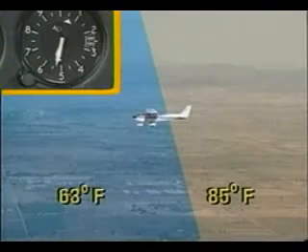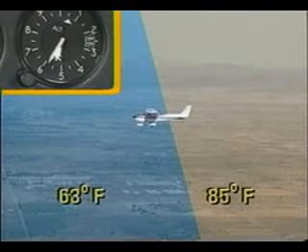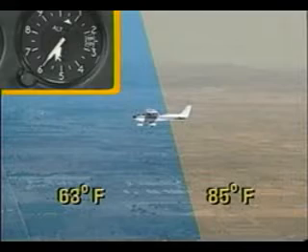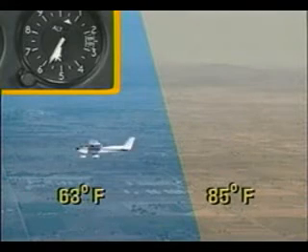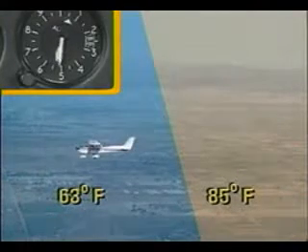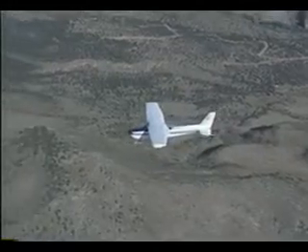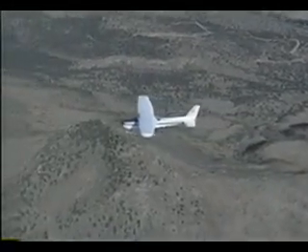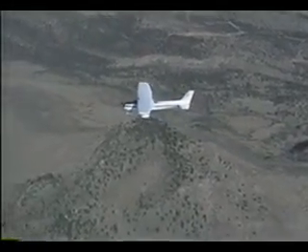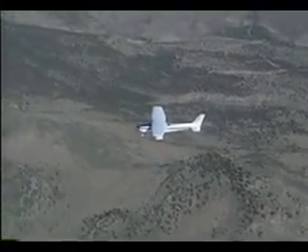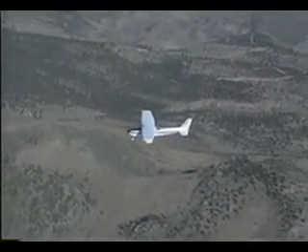To a certain degree, this same situation occurs when you're flying from an area of warmer air to one with cooler air. Obviously, this could be dangerous if you're flying over obstacles or high-rising terrain. It could also place you far off your appropriate VFR cruising altitude.